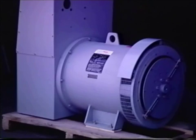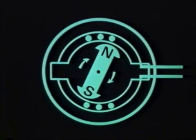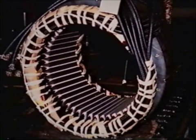Now, here's where LIMA comes in. All LIMA generators are revolving field alternators. There are no slip rings or brushes, and all output leads and connections are stationary. Revolving field simply means the field rotates and the armature is stationary. Let's take a closer look at a stationary armature and review its construction and principles.